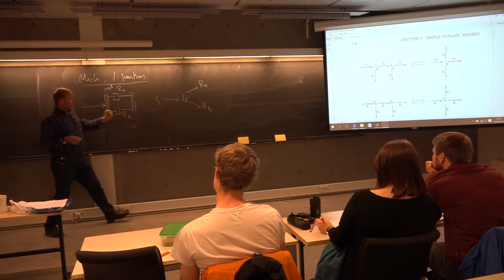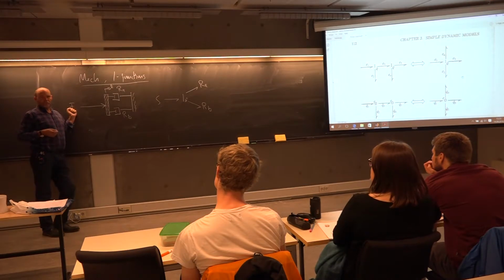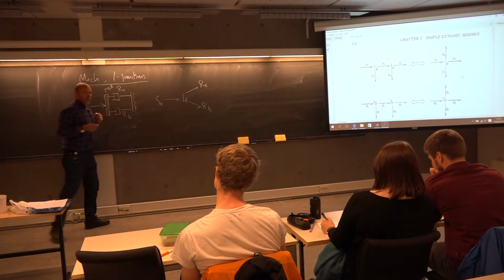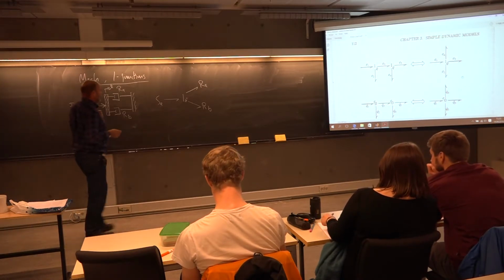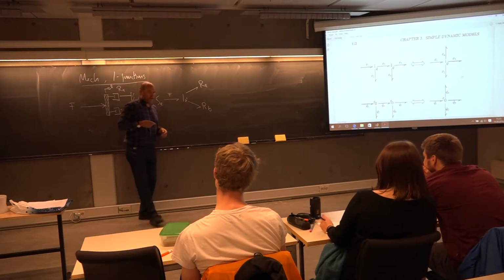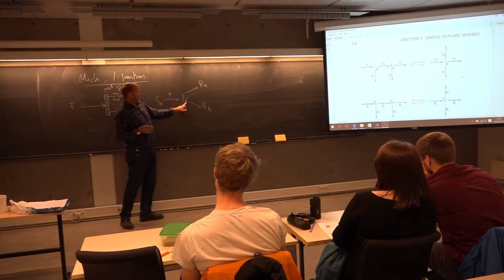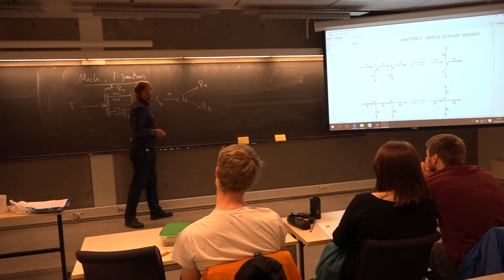This source will be a force. What kind of source is that? Well, that is an effort source, so you will write S_e. Here the effort will actually be the mechanical force in Newton, and the flow is given by x dot, which is the same on all these three bonds.